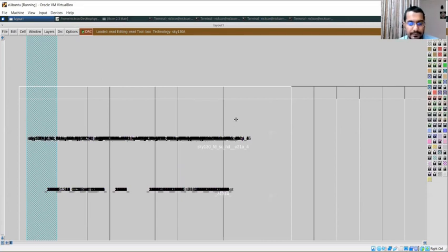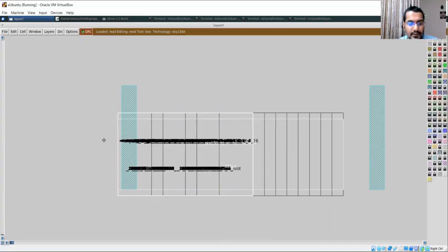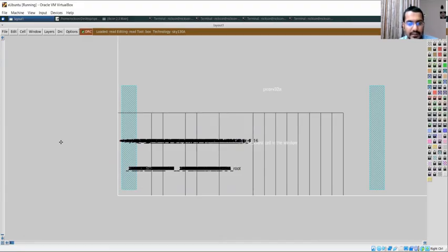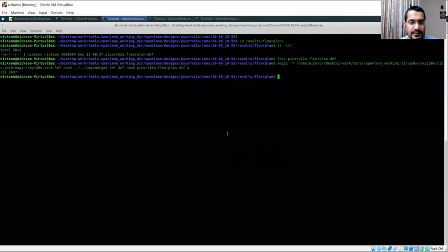So this is all about floor plan. I would request you to just play around with all these switches and see what effect they make. Just change the input output pin mode from 1 to 0, but it's always good that if you're making any changes, you make the changes in the design related config file so that it's more flexible. So I will just center this design, S and then a V. So this is our design, this is our floor plan. So next, I'll just close this quickly, and yes.